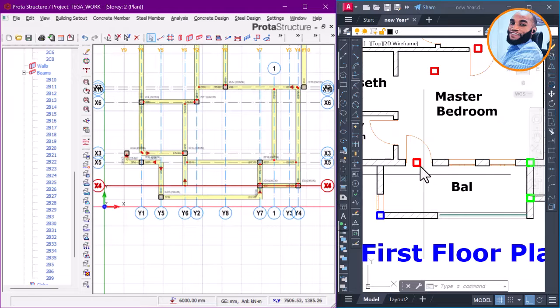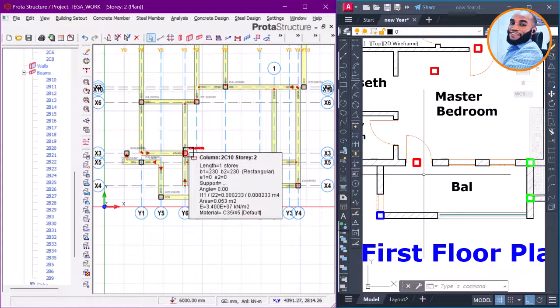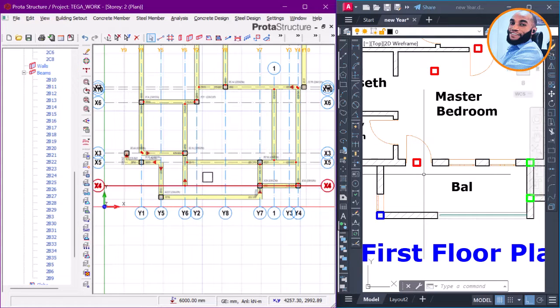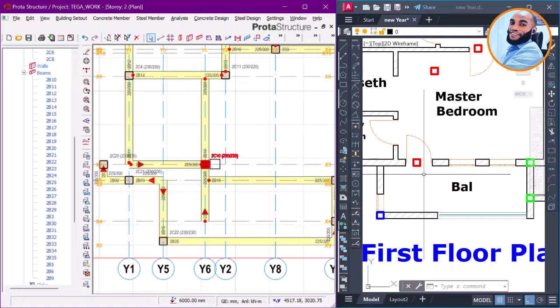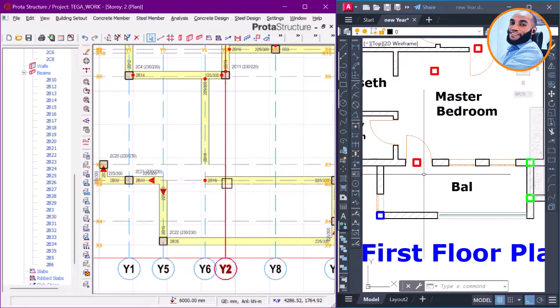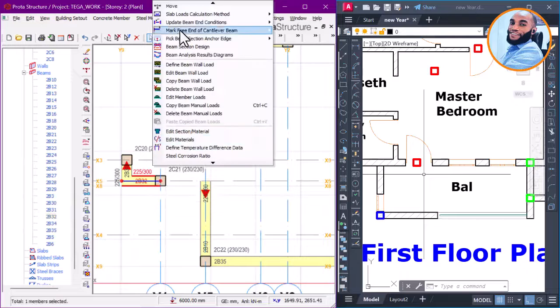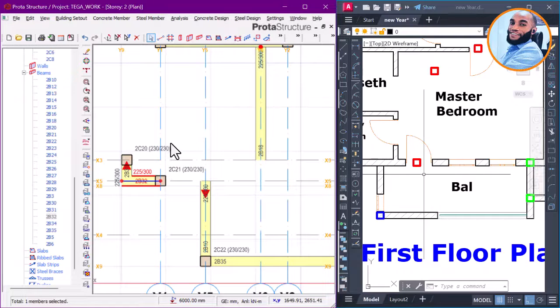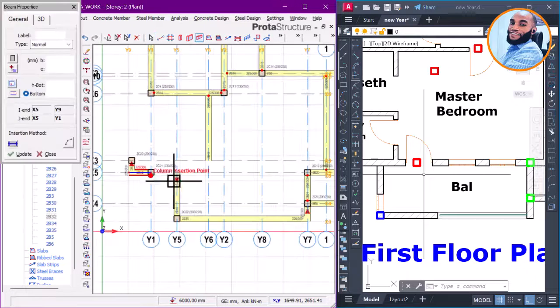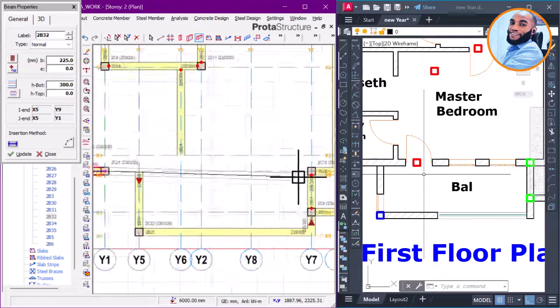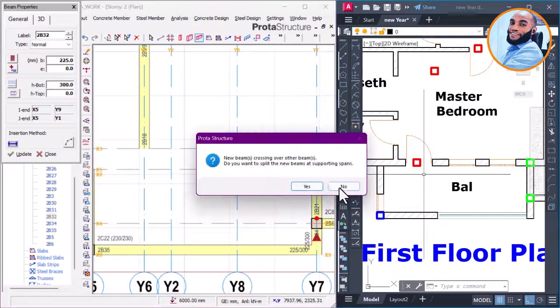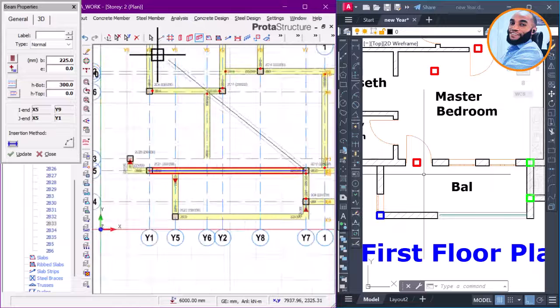And then what again right now, this column here at the door, which is this one here, is meant to go off. Okay, it's meant to go off. So right now, take it off also, remove this beam, remove this, and remove this, and then throw a long beam from here all the way down here, because this is a roof beam. So let me see, if the length is less than 8 meters, it's okay. So let me just check what the length is.